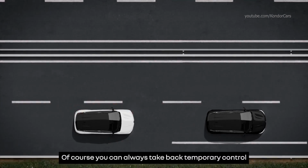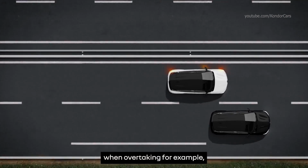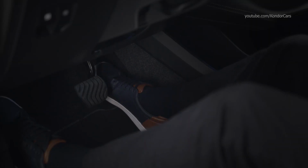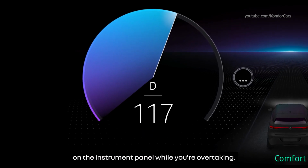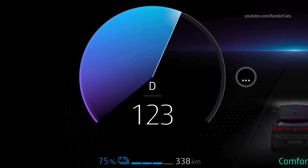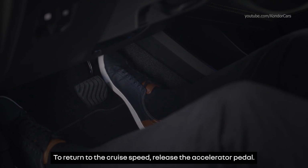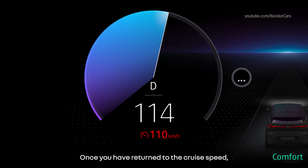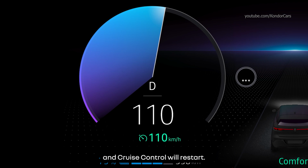Of course, you can always take back temporary control of the vehicle acceleration when overtaking, for example, by pressing the accelerator pedal. You'll see the cruise speed flashing red on the instrument panel while you're overtaking. To return to the cruise speed, release the accelerator pedal. Once you've returned to the cruise speed, the instrument panel display will go back to normal and cruise control will restart.